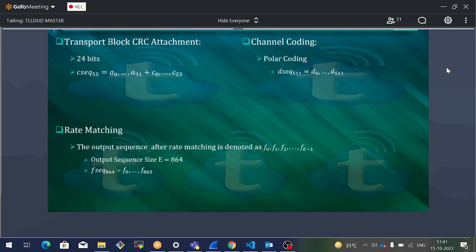Because for the available amount of PBCH symbols, you actually have 432 symbols available for PBCH operation, again from the same table that I showed you. Because you are using QPSK modulation for PBCH, the lowest modulation, each and every symbol will be able to send 2 bits. So it can totally send 864 bits. But the actual available data is only 512 bits. What do you do? As part of rate matching, you do the matching. So you added some dummy padding and made sure that it perfectly fits into the size that is available.